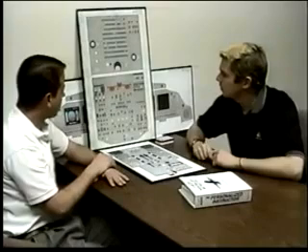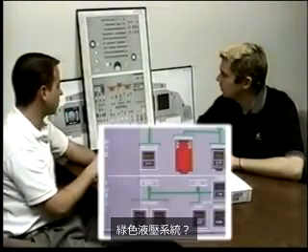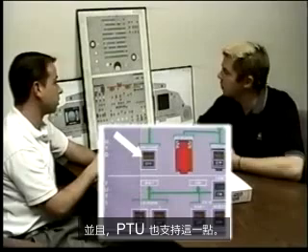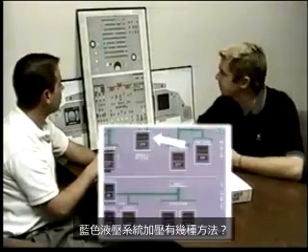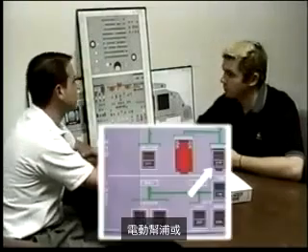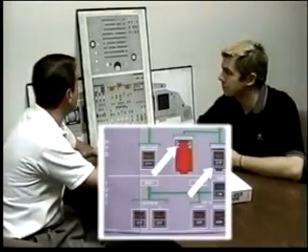Hydraulic panel. Starting with the green system, how many ways to pressurize the green hydraulic system? Just the engine-driven pump. Anything? And, well, the PTU backs it up. How many ways to pressurize the blue hydraulic system? Either the electric pump or the ram air turbine.